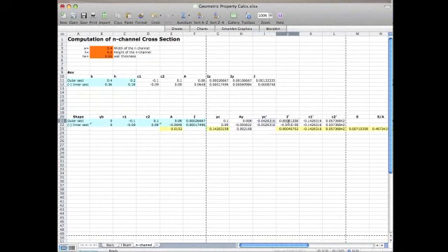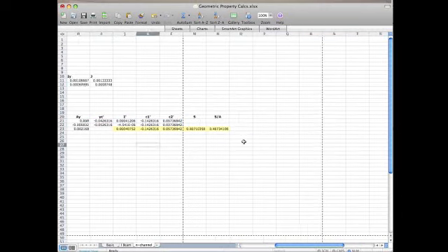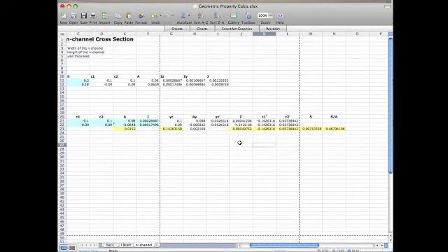And likewise, then it computes I parallel axis, and then computes the outer fiber distance for each section, and then picks the max. So all the rest of this stuff you don't have to touch. You really just have to touch these and figure out how to add them together. All right, and so then that gives me, finally, the inertia of that section,